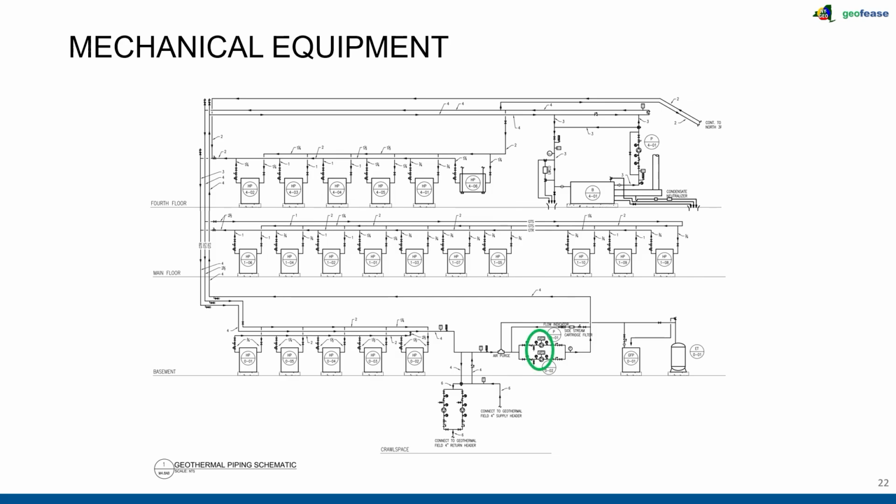It can be a big portion of the COP, or the system coefficient of performance. Understanding the electrical energy of the heat pumps as well, maybe water to air heat pumps. In this case, if we understand our thermal energy and we know our electrical energy, we can get our COP. That ratio is our coefficient of performance.